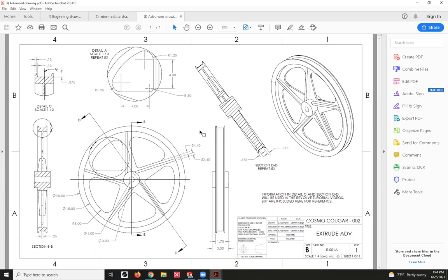One thing I notice when I see this wheel that I want to use while modeling is that if I were to draw a line down the middle of this, I can see that it's symmetric on both sides. I can make that assumption. And so when I model this, I'm most likely going to use the mid-plane extrudes because that will allow me a symmetry, as we saw in the last video, which will make for more efficient modeling.